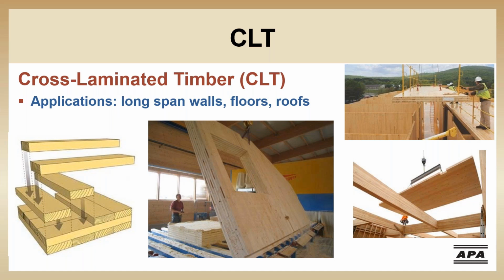While at the mill, the CLT panels are going to be cut to size, and this is going to include door and window openings. These are cut with state-of-the-art CNC routers, and they're capable of making complex cuts with really high precision. Finished CLT panels are going to be exceptionally stiff, strong, and stable, handling load transfer on all sides. The panels can be manufactured at custom dimensions, but it's always important to check with each manufacturer, as transportation restrictions might dictate their length.